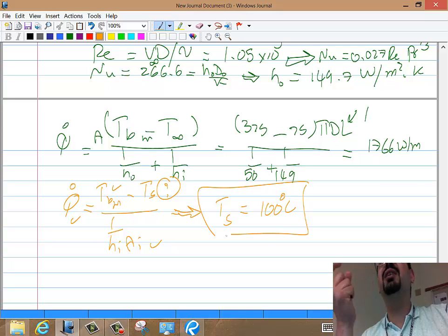Now, if you have another really weird fluid that has huge variation in properties, maybe in that particular case 1 degree would be a big deal, because the viscosity changes a lot and the k jumps. So it's really the property that tells you whether you should go again or not.